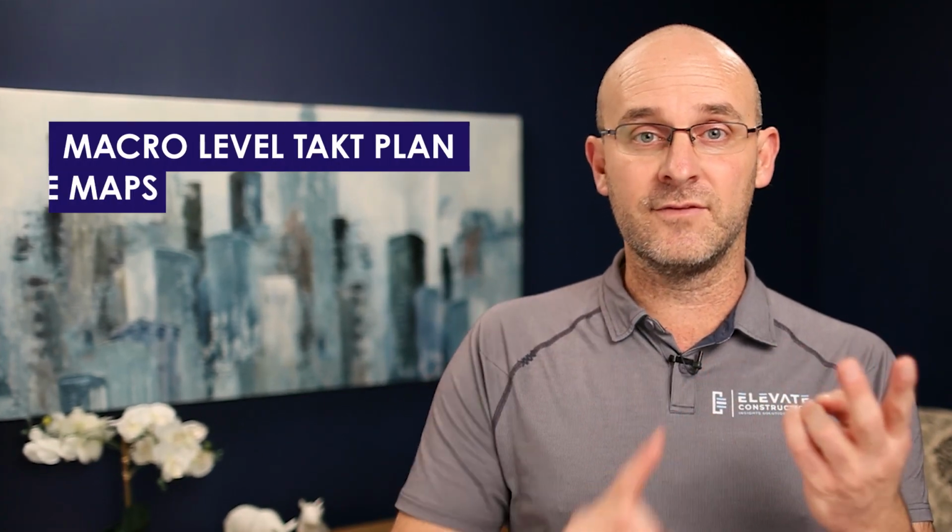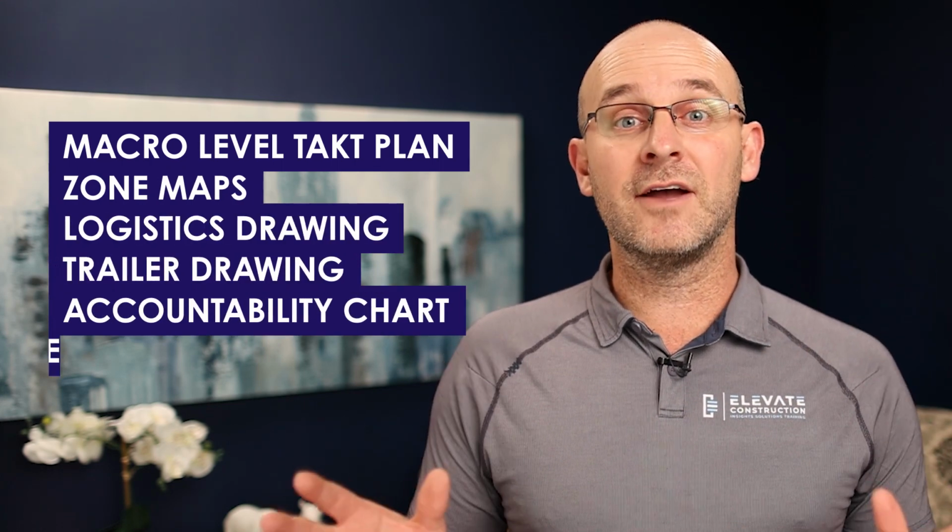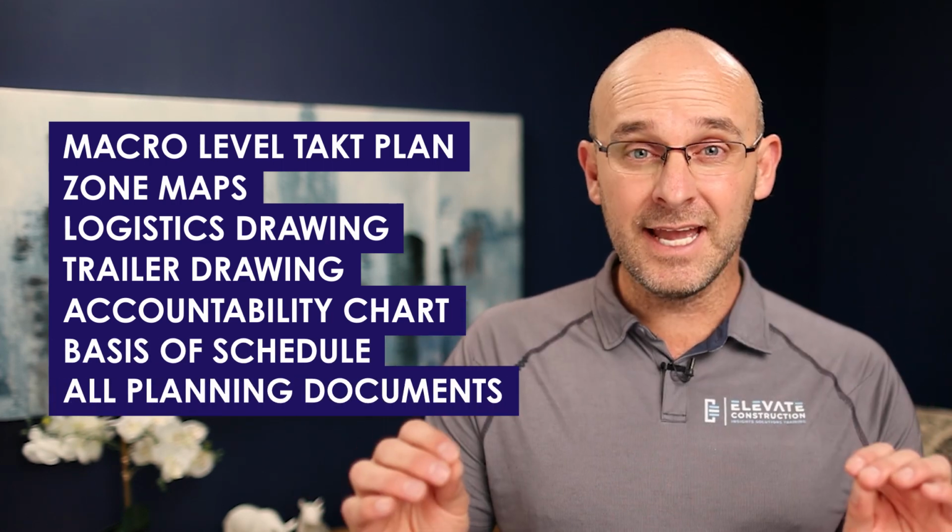So, like I said, by that time, you have a macro level TAC plan, you have your zone maps, you have your logistics drawings, you have your trailer drawing, your accountability chart, you have your basis of schedule, all planning documents. And through your constructability reviews, now you and the design team have finalized a set of construction documents or contract documents that should clearly articulate and communicate the design. So now you should have everything you need and the certainty to go ahead and finalize your budget and establish a GMP, a guaranteed maximum price, and to submit your final GMP submission and to sign the prime agreement.